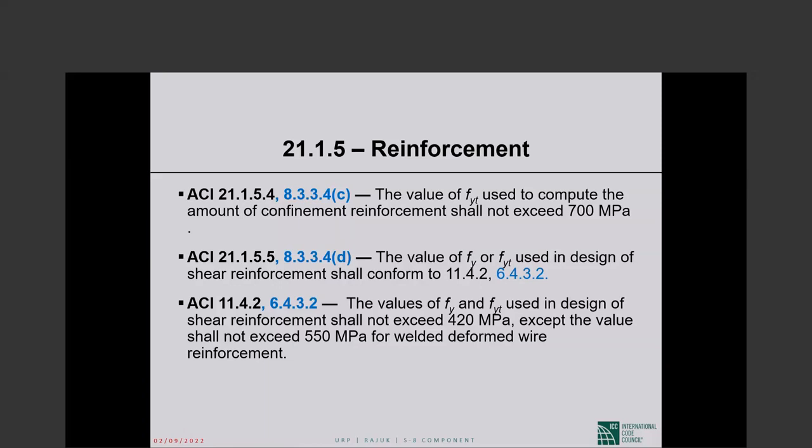Anyway, I think you have to fully understand what is being said. So transverse reinforcement, when you are designing it to confine the concrete, your strength limit is 100 ksi. And this is very, very important, as I'll explain next. Extremely important. It took a lot of work to get this 100 ksi approved as early as ACI 318-08.